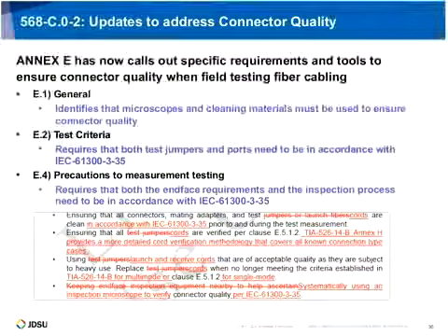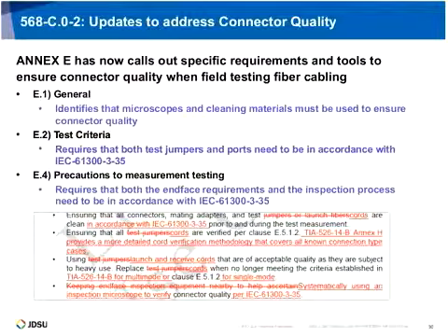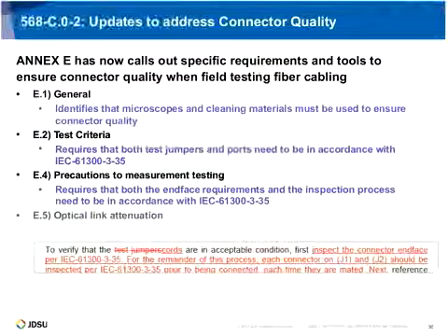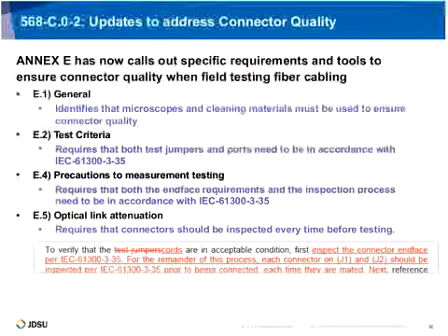Third is that the end-face requirements need to be in accordance with IEC. Again, the term IEC 61300-3-35 shows up in multiple places now in the 568C standard. And then last, it requires that connectors should be inspected every time before testing.